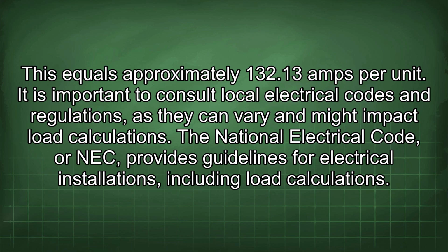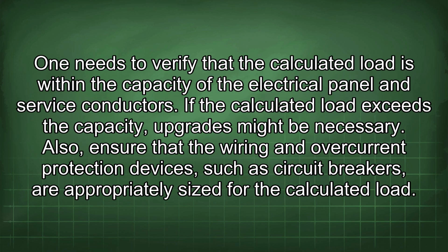It is important to consult local electrical codes and regulations, as they can vary and might impact load calculations. The National Electrical Code, or NEC, provides guidelines for electrical installations, including load calculations. One needs to verify that the calculated load is within the capacity of the electrical panel and service conductors. If the calculated load exceeds the capacity, upgrades might be necessary. Also, ensure that the wiring and overcurrent protection devices, such as circuit breakers, are appropriately sized for the calculated load.